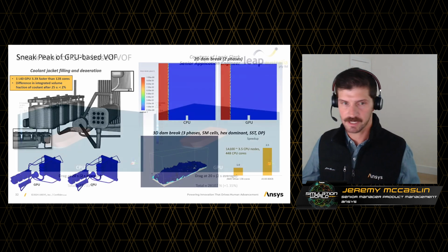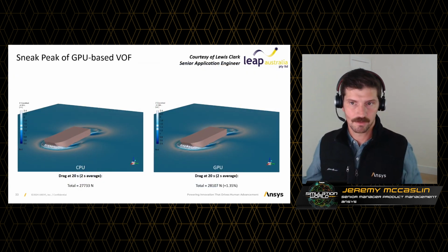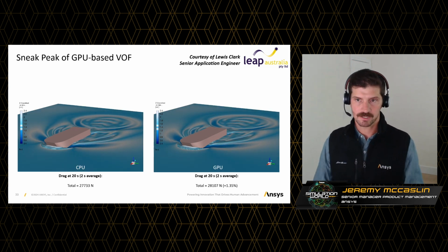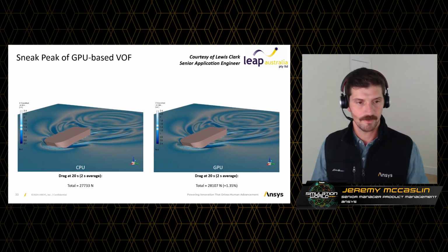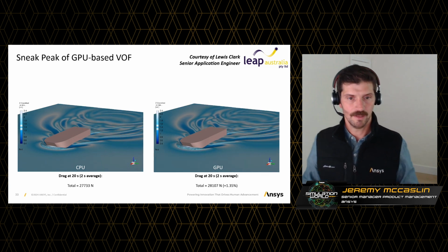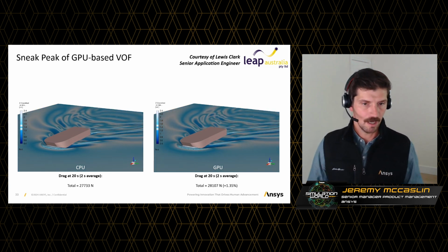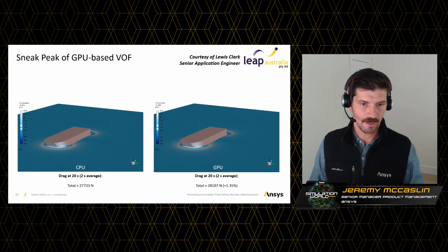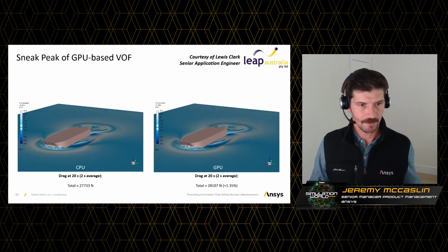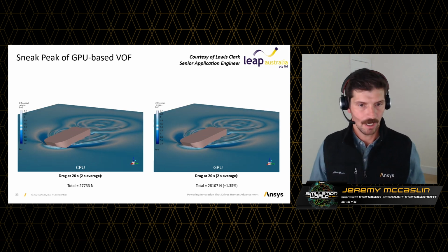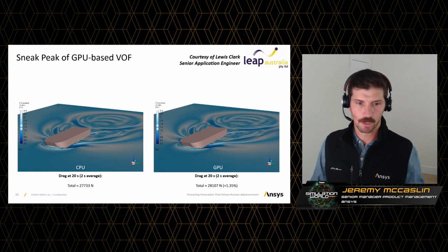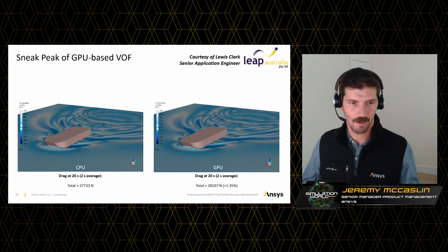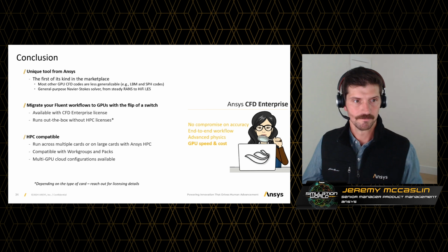In this next slide, courtesy of Lewis Clark from Leap, he was doing some early testing of VOF on the GPU, and here we have this marine application where you can see the CPU and GPU results side by side are very much indistinguishable from one another, and the total drag on that ship is a little more than 1% different between CPU on the left and GPU on the right. So we're very excited about how things are coming along with VOF.